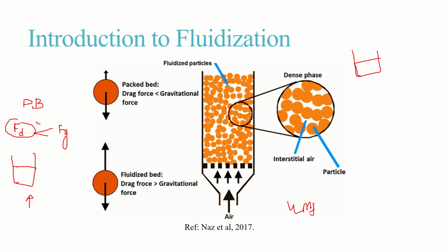They would not remain in the packed condition, but rather remain suspended in the fluid, though not moving, in a kind of loosely packed manner. At that point, the particles are becoming very loose, and the weight of the particulate system, that is the fluid and the particles, is balanced by the gravitational pull. So this is known as the minimum fluidization condition.